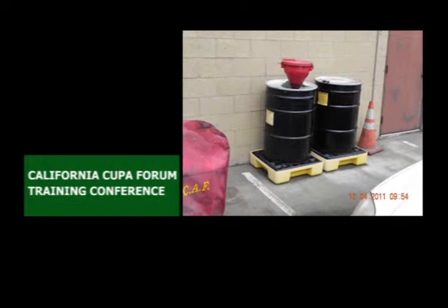All right, smart guys. Drum set, what kind of containment do these things have to have? Size, contain 55 gallon. Nah. Now, people who sell containment pallets, they sell all kinds of containment pallets, right? You need to check the specs. Some are 5, some are 11, some are 66. And that's a problem with a lot of facilities. Hey, go buy some containment pallets for these drums. And they grab the New Pig catalog, they grab the McMaster-Carr catalog, and they buy anything that looks like that. No, they sell some that are not adequate for the required volume, for different uses.